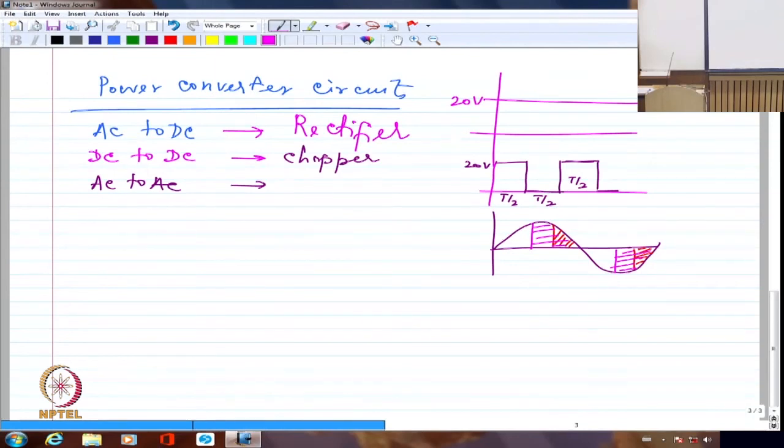I can simply have an on-off switch in the positive direction as well as the negative direction. So imagine I have one diode like this, another diode like this. But if it is a diode, I can't control it, so I have to have another gate terminal. The gate will open the conduction or close the conduction. So generally we call this terminal the gate, this terminal the anode, this terminal the cathode. 3 terminals. Right?